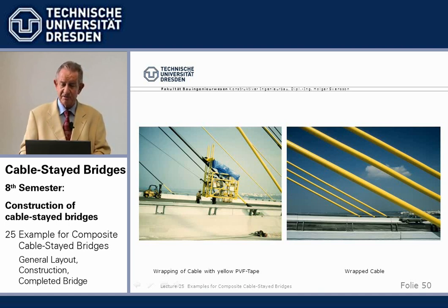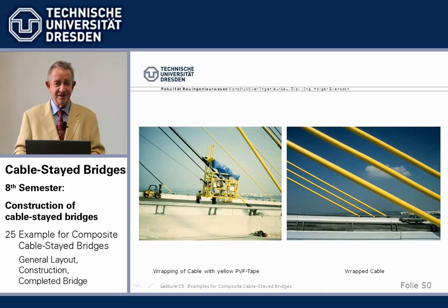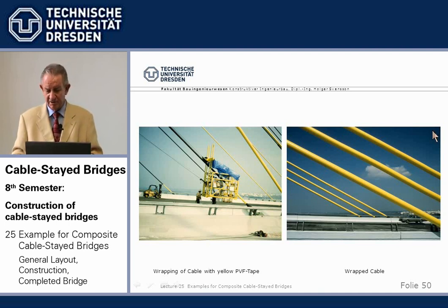PVC is not, as we found out, but we found PVF tape, polyvinyl fluoride, which is UV resistant, nicely colored, brand name Tedlar, and that's what we used and had lots of tests done. So we wrap the cable, and then we sink against the dark blue sky and the intense sun in Texas. That looks very nicely.